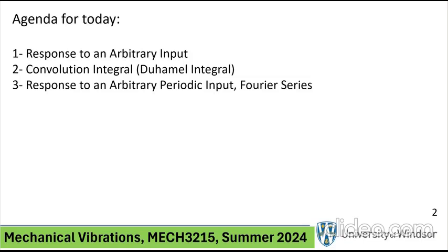That expression, you can go check it out, and you'll see it again today. I also said that if this impulse was applied at a different point in time, not at t equal to 0, then the response, again the impulse response, has the form h of not t but t minus tau, if the impulse is applied at time tau. I mentioned that you may not see why this is so important, because it's going to come back and help us when we try to solve the same problem where the force is an arbitrary function f of t. And that's the crux of the lecture today. Have fun.